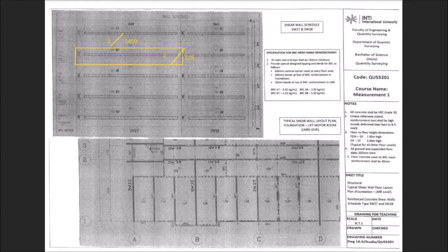Okay, I show you the height here. The height must be shown in the side cast. Always remember, as what I told you before, the height is given as 3,900. But you cannot take this one directly because the information of the slab is given as 200. So you have to deduct the upper floor slab, deduct 200. You get the height as 3,700.